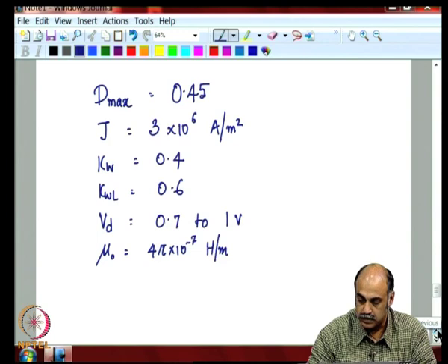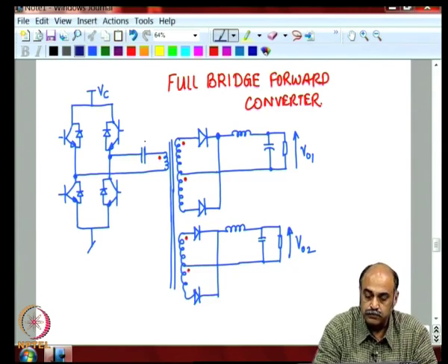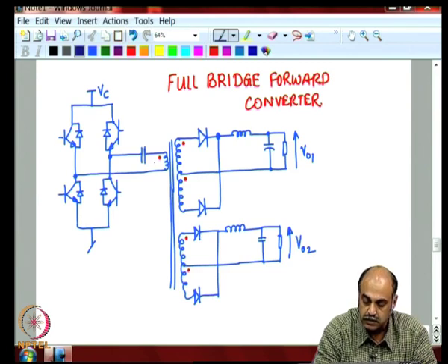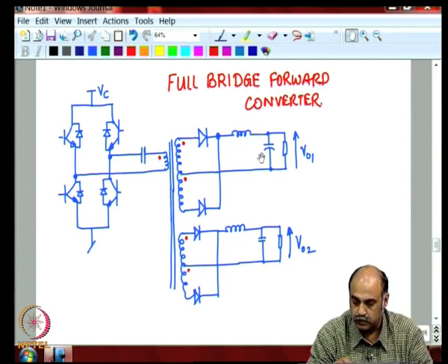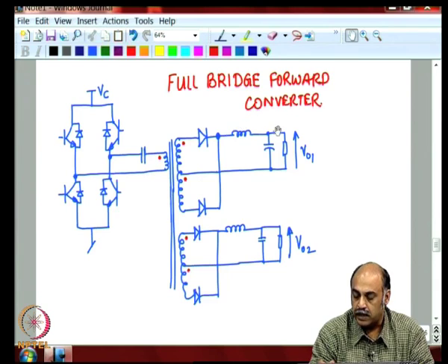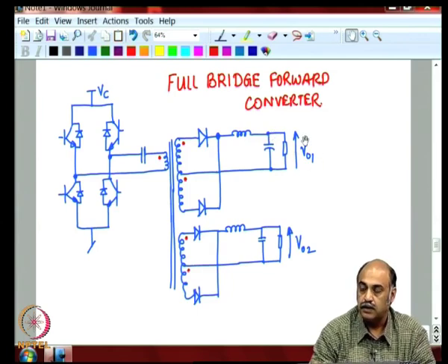Now, if you look back into the circuit, you will see this is Vc minimum, this is the worst case, minus around 10% of Vc max, which drops across this capacitance. So, that would be the voltage that occurs at the primary of this transformer. Now, n times will be transferred onto the secondary here, and with all the various drops just discussed. Okay. So, into d max times, because if this is minimum, the max duty cycle would be maximum, would be what the value that you would get here.